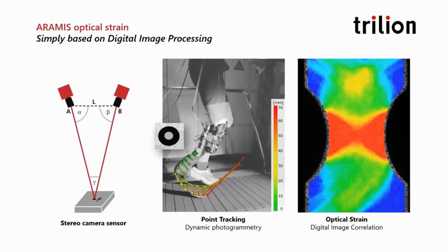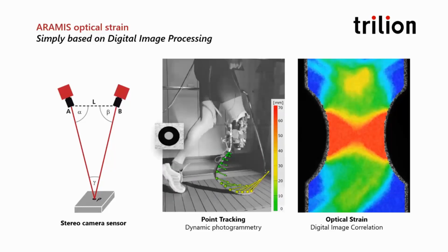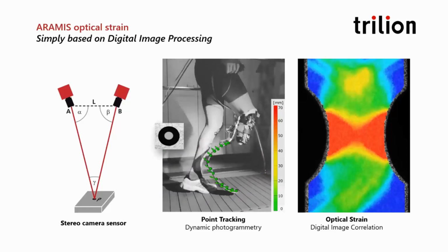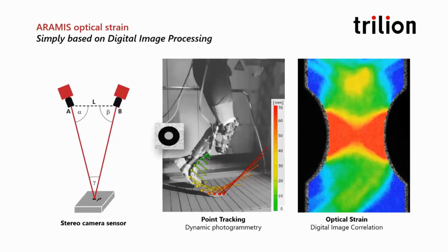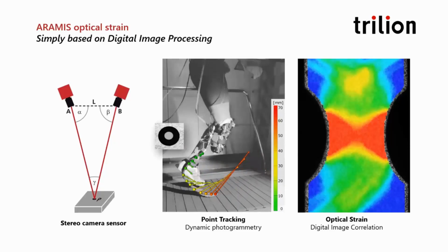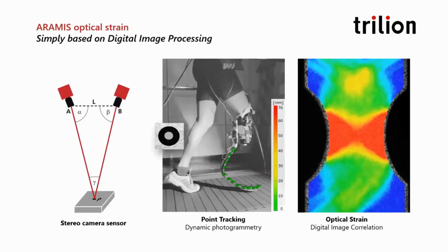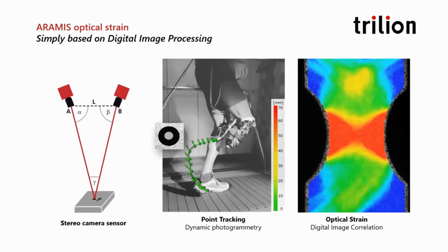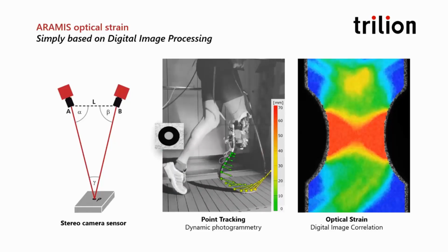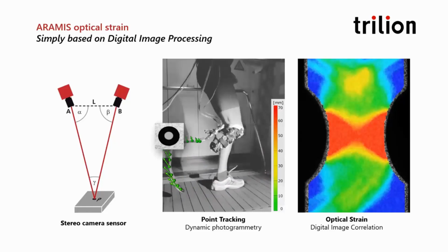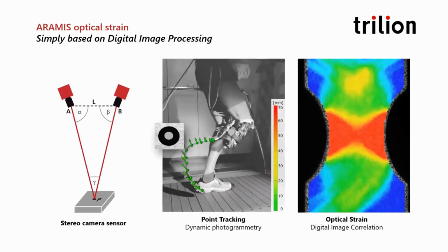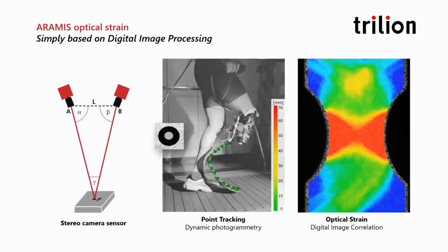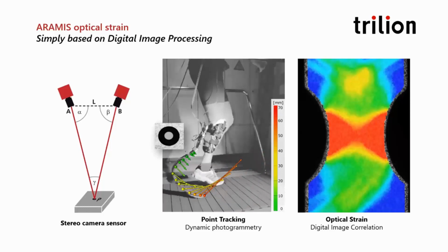So here you can see a test with a person running at up to 10 kilometers per hour, and we're capturing it at 200 frames per second. This is a really narrow structure, and it has just small, lightweight adhesive dots. These are target dots, and we can measure the bending or stiffness of the prosthesis by placing these dots down. So this is a relative displacement measurement, with the dots along the blade measured against target dots on the knee.